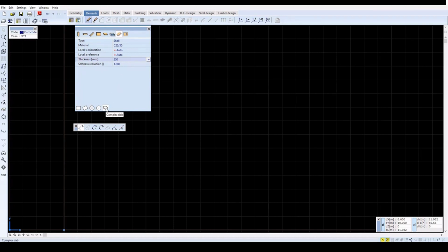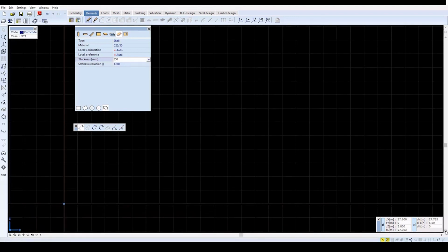Firstly, we'll draw the side wall of the reservoir in the XZ plane. In the XZ plane view mode, choose the origin as the first point of the polygon. Move the cursor to the next point and click to define each vertex. From the origin, click 11 meters right and 0.2 meters down.